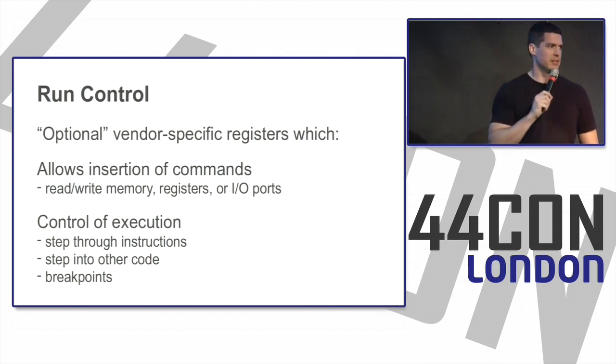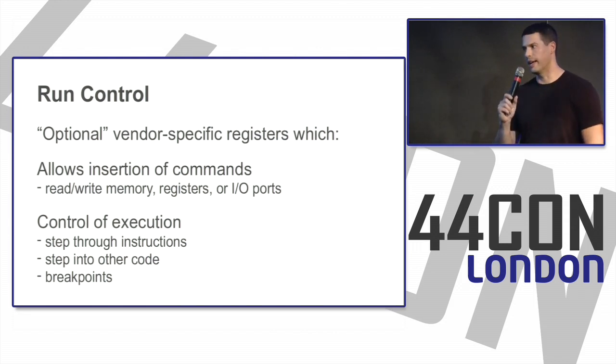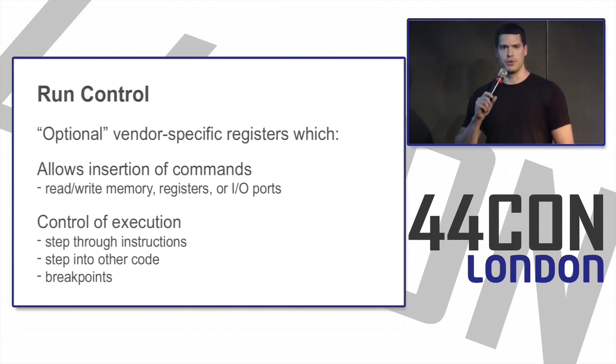And this is really in there because if you are trying to debug software on a microcontroller and you're running on the absolute bare metal, nothing underneath it, no kernel, no hypervisor, nothing else there, and it doesn't work, you're either stuck or you can use this. I have never actually seen even the tiniest, most proprietary, barely supported little microcontroller with no software development environment. Every last one of them I've ever seen has at least some rudimentary form of this that allows you access to go in through JTAG and sort of poke at what's going on in the controller.